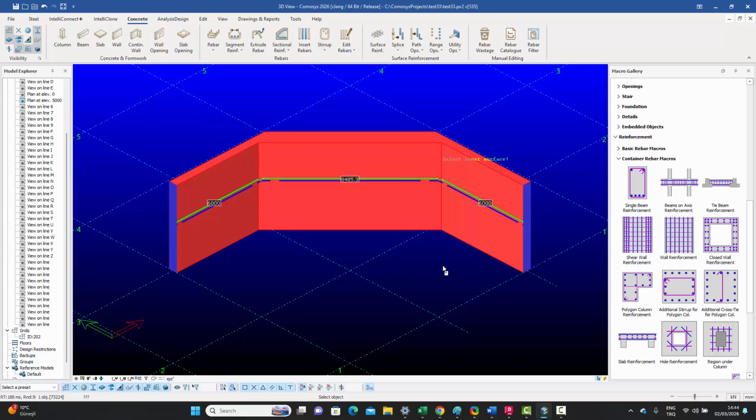And then after you've chosen the start and the end, it's going to ask for an inner surface. So if you come over any one of these, you can show the inner surface. It's usually a good idea to show the one near the start. It could be any one of these. So there's an inner side and then there's an outer side, and we'll have the settings for those. To tell the program which one is the inner side and which one is the outer side, you can just select this inner one over here.